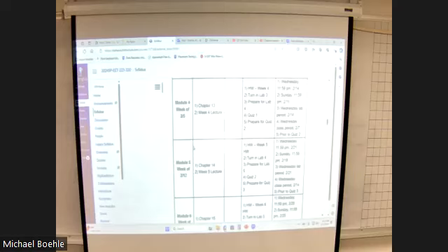So when I do my review and we talk about Ohm's law, Ohm's law is for what? Resistance, right? Well, it turns out that for capacitors and inductors, when I put AC on them, they generate something called reactance, which also has the units of ohms. So we can actually apply Ohm's law with reactance. Okay. So you see that in chapter 13 and 14. We'll get into that in a little bit more detail, talk about what reactance is, phase shift, and everything else.